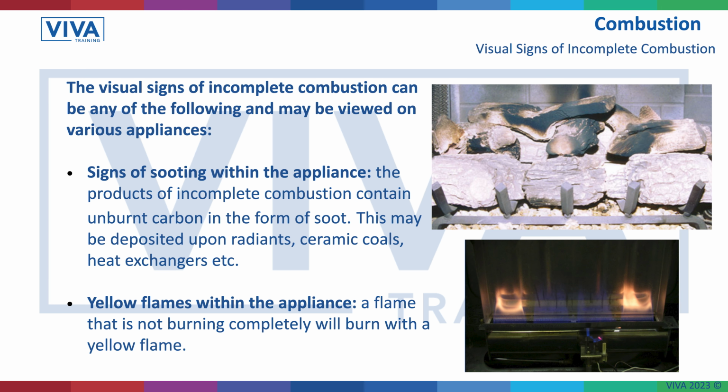That's a fire there. That's what's called a duplex burner. It's actually 4 flames or 4 burners. The middle 2 light independent of the outer 2. And the middle 2 are burning reasonably well, quite a decent blue flame, but the outer 2, that's where the injector, the air port, has been drawing some dust or fluff, or somebody's cleaned the injector out and enlarged it, so it can't get enough oxygen in for the volume of gas that it's burning. So again, that's not burning correctly. That would trigger me to say, look, that appliance needs checking, probably needs a good service on that one.